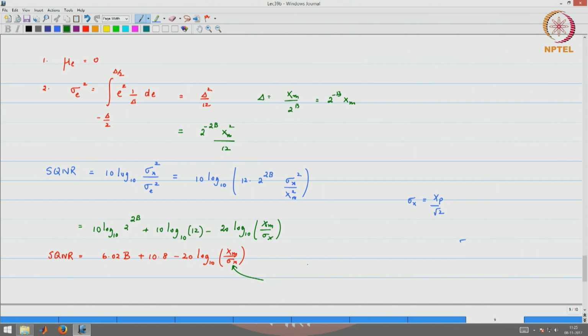So you can say, for example, that I will choose xm to be equal to 4 times sigma x, basically 4 times sigma on this side, 4 times sigma on that side. So that is the range that I want to cover. If you take some assumption like this, you are bound to capture most of your input signals. Of course, there could occasionally be an input sample that goes outside, but by and large you have captured it. You can do 3 sigma, 5 sigma, whatever it is. Keep in mind that the larger you keep x of m, the more it is going to reduce your SQNR, because with a finite number of bits, your quantization error is going to be more since you have a larger range to cover. So this is an important choice.